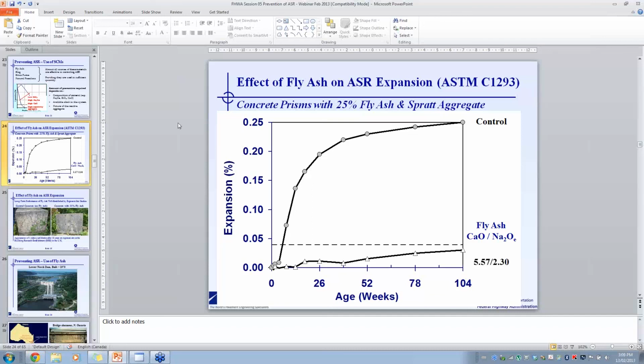So certainly that's changed. But fly ash produced from a given coal source wouldn't be that much different because of processing controls. Some stations are running low NOx burners nowadays. That might tend to have a slight impact on reactivity and possibly carbon content. But the main change is the different source of coals that's used. Of course, some other stations are injecting things into the boiler for emissions control, and that can impact the fly ash too.